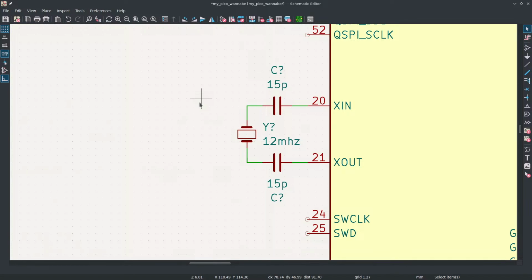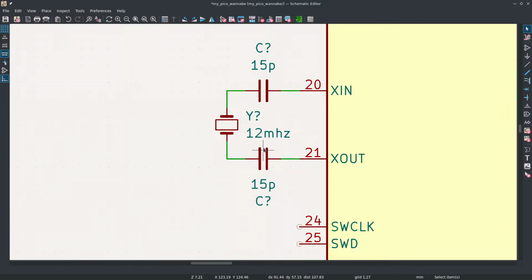By the way, the 12 megahertz crystal is chosen on this, I guarantee you, because USB is at 48 megahertz, which is an even multiple of the 12 megahertz. So they need a 12 megahertz reference. What does X in mean here? Crystal. X or Y are usually the letters you find associated with crystals. You can see how X crosses, so crystal, or X-Tal.